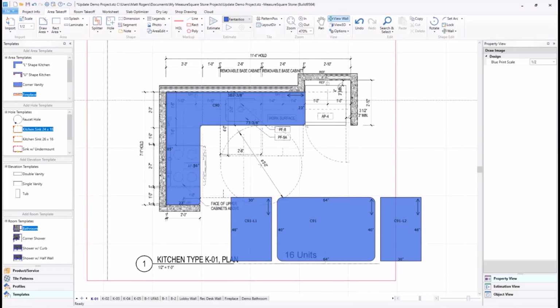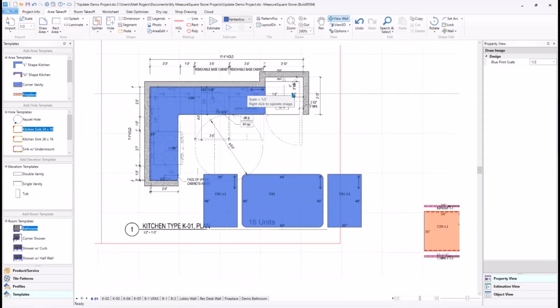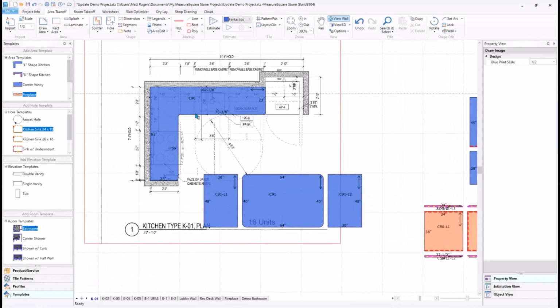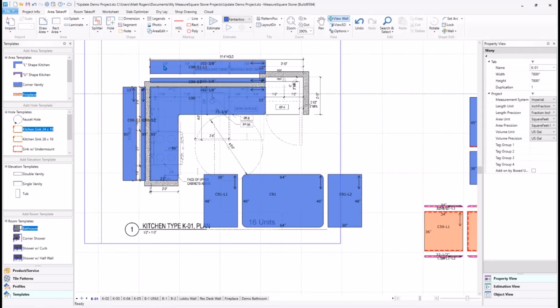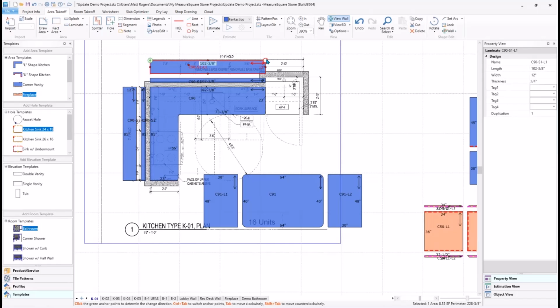All right, awesome. So I think that covers most of the things here in quickly drawing these takeoffs. The last thing we might want to add for something like this, again, we have our splash tools. So again, I can just add some of these in here. If I want to, I can come in here and actually add a second layer laminate to something like this top. And what that's going to do is just add another edge, essentially kind of a top here. It would be kind of like a bar top to this piece. So if we wanted to extend this, we'll say 12 inches. The only thing I might want to do is then extend this side here to maybe 114.